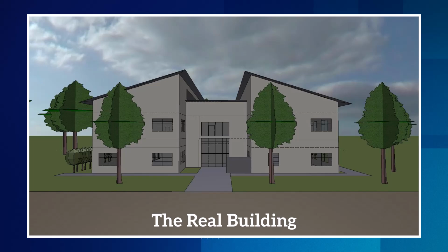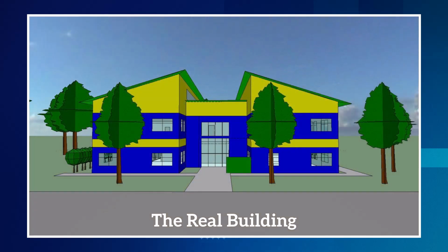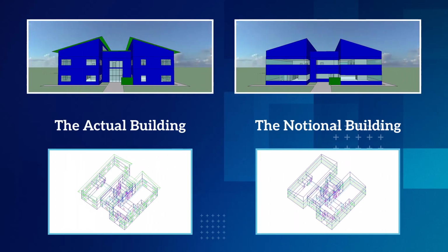The real building is the closest to our design building. We might use it for design studies such as overheating studies, natural ventilation studies, SBEM loads calcs, etc. We would run these simulations within Apache as they are not tied to UK compliance. We then have the actual and the notional buildings, which need to comply with requirements in the building regulations. So we work on them within the UK compliance application in the VE.